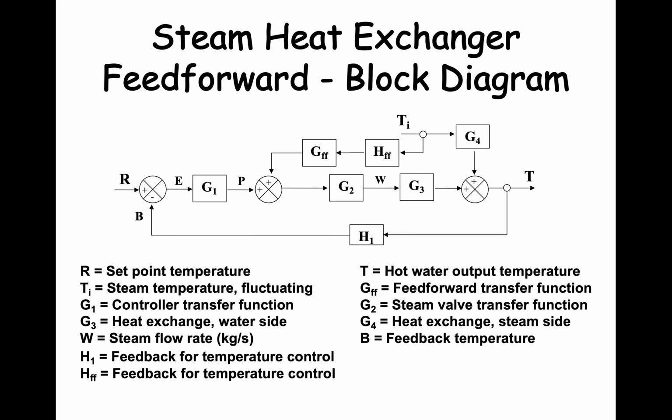Here is the block diagram for our steam heat exchanger. We add a sensor to the inlet steam temperature line and run the sensor signal through a transfer function named HFF, which supplies a feed-forward control GFF.